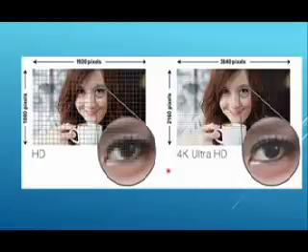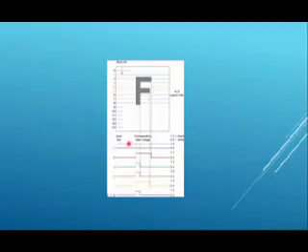The greater the number of scan lines, the higher the resolution and the greater the detail that can be observed. US TV standards call for the scene to be divided into a maximum of 525 horizontal lines. The electrical signals derived from each scan line are referred to as the video signal. Shades of gray are represented by some voltage level between 0 and 1 volts, with the extremes represented by white and black. The resulting signal is known as the brightness or luminance signal and is usually designated by Y.